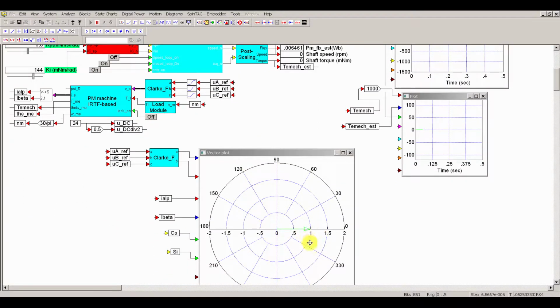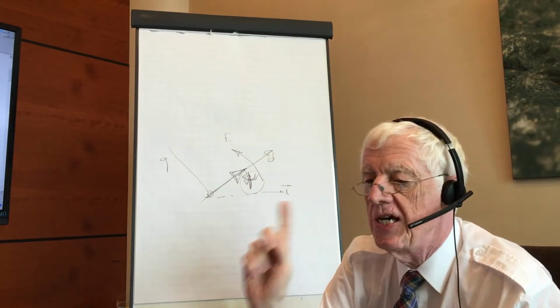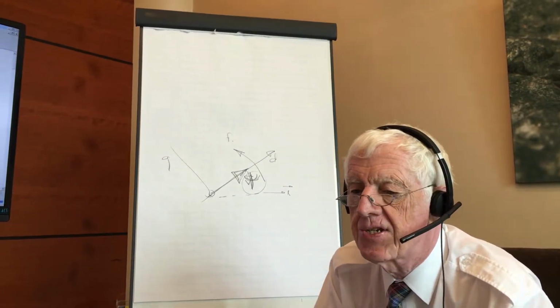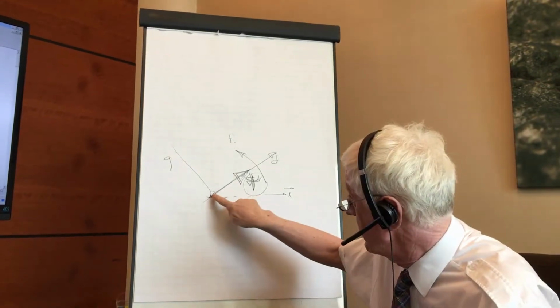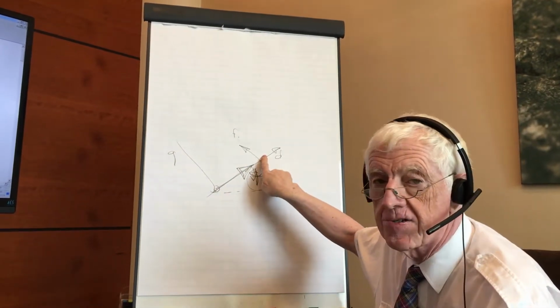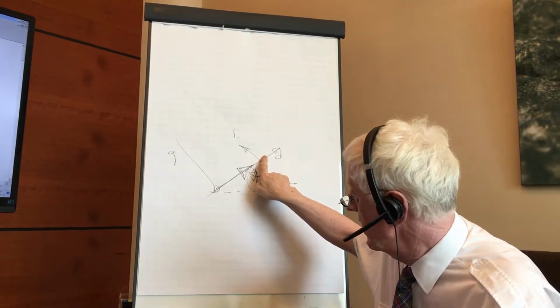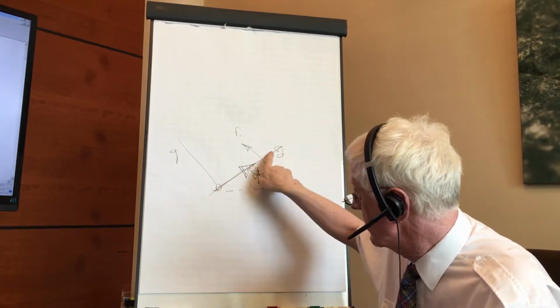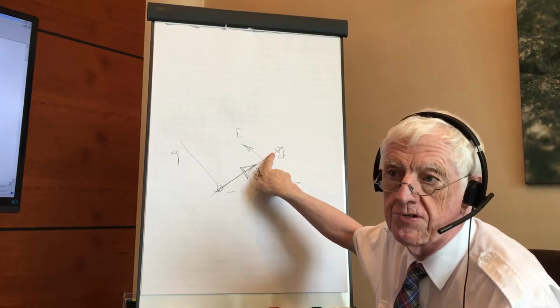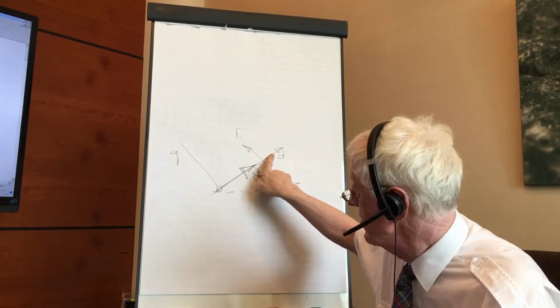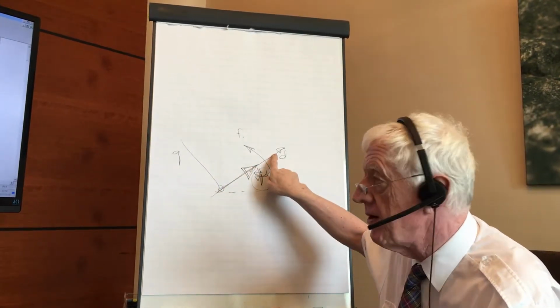This is the d-axis, this is the direction of flux. It's really important. Nothing happens. Now, if I apply a d-axis current, a current in the same direction as the flux, then the theory will tell you, if you put current in that direction, there will be no torque produced. And no torque means it's not going to go anywhere, it's going to stay there.